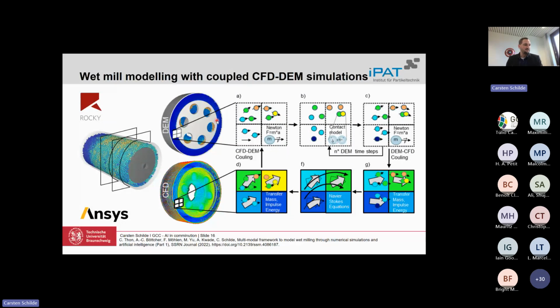For the model we want to set up, which is then used within the grinding population balance modeling approach, we want to introduce a real stressing energy curve or intensity curve of our mill within our population balance model of the machine function, which is then related to the breakage rate as well as the breakage function.